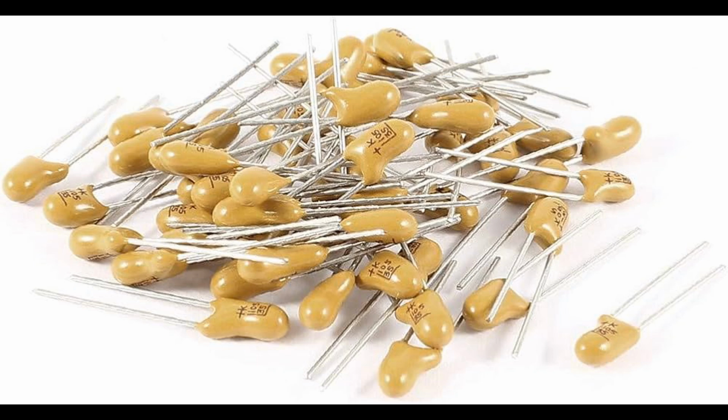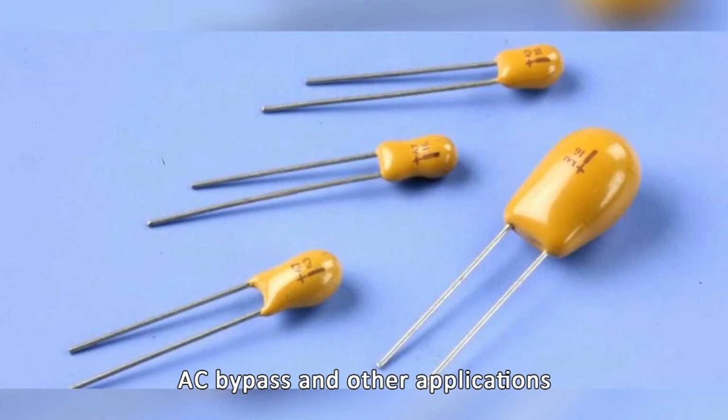connected correctly to function. Here's a detailed breakdown of how a tantalum capacitor functions. 1. Basic structure. Anode, positive terminal. The core of the tantalum capacitor is a piece of tantalum metal that forms the anode. This tantalum is porous, increasing the surface area and allowing for more capacitance in a small volume.